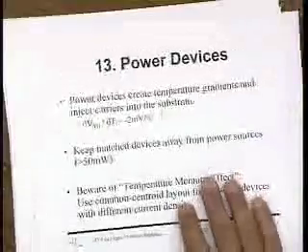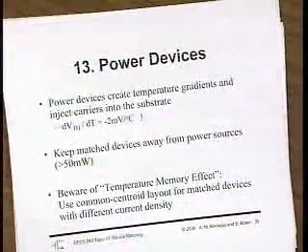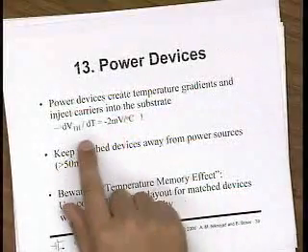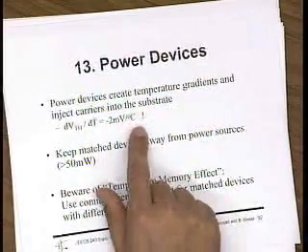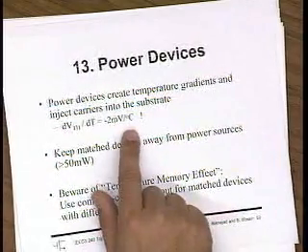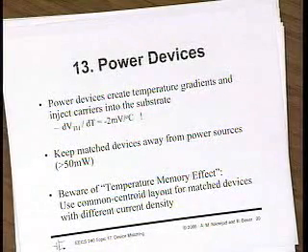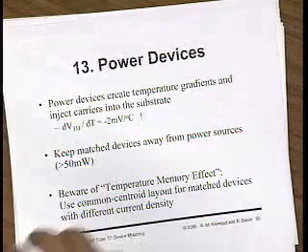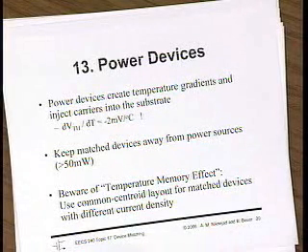One final point is temperature, something we usually don't think about. If you look at the temperature dependence of threshold voltage, it's about 2 millivolts per degree C. That's huge, right? If you've got a transistor that's driving an external load and it's dissipating tens of milliwatts, maybe hundreds of milliwatts, it's going to run hot. And so that's going to create a temperature profile across your die. Where the power transistor is, maybe you're 10 degrees hotter, and then as you move away from that power transistor,